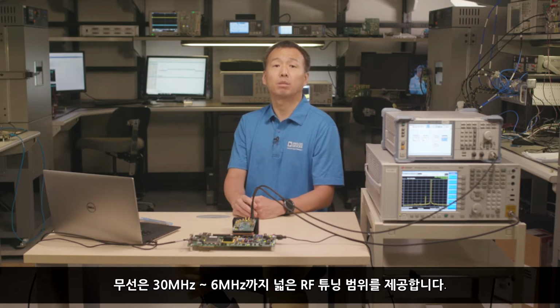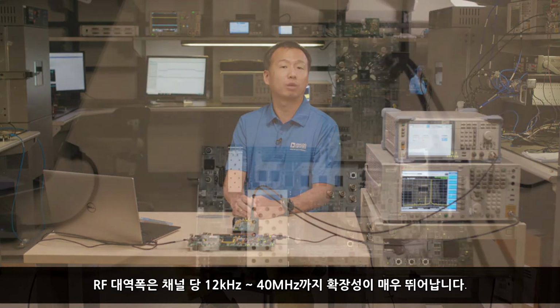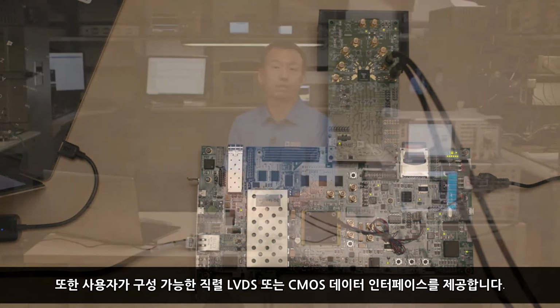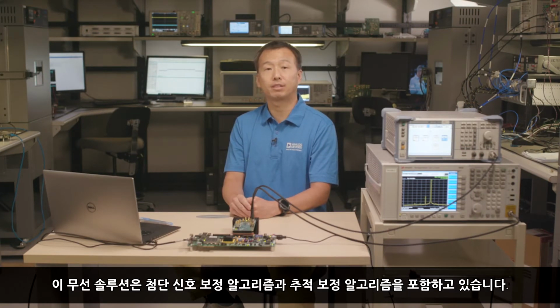The radio provides a wide RF tuning range from 30 MHz to 6 GHz. RF bandwidth is highly scalable from 12 kHz to 40 MHz per channel. It offers user-configurable serial LVDS or CMOS data interface. The radio incorporates advanced signal correction algorithms and tracking calibration algorithms.